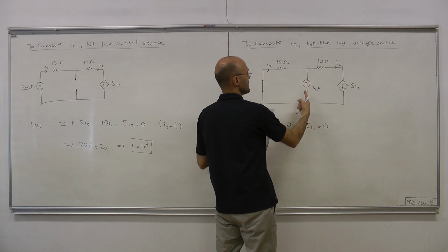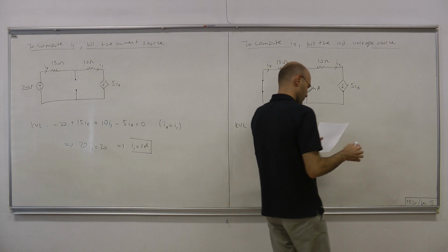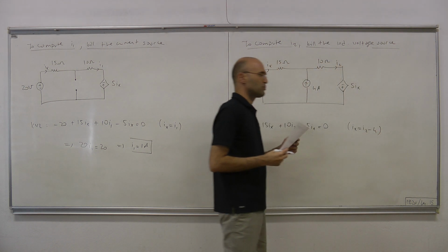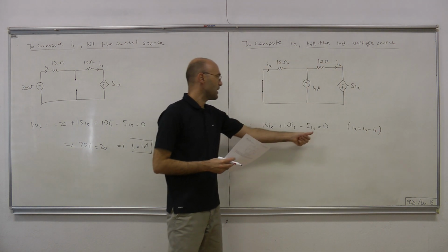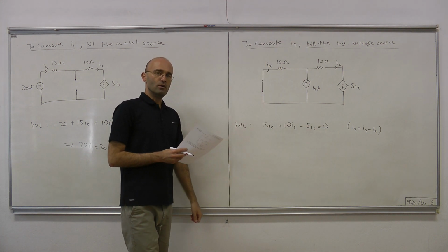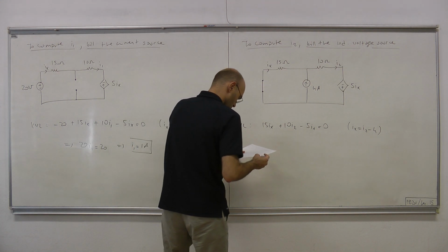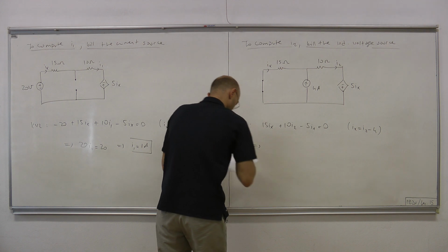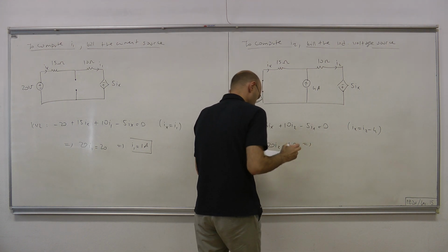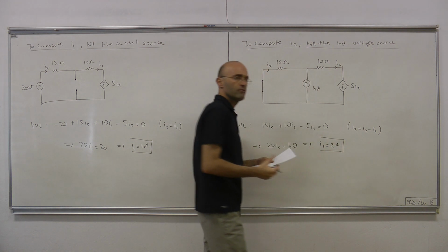Okay, ix plus 4 equals i2. Therefore, ix equals i2 minus 4. So we can express ix in terms of i2, replace that ix with this expression, and then the equation becomes only in terms of i2, and then we can easily solve for i2. Okay. This time we have 20 i2 equals 40, which gives us i2 equals 2 amps.